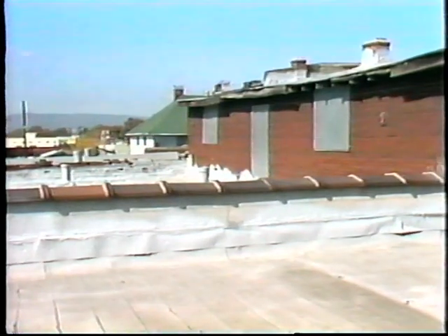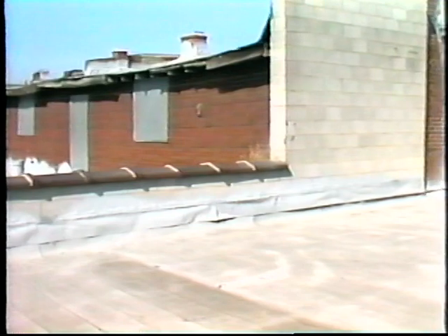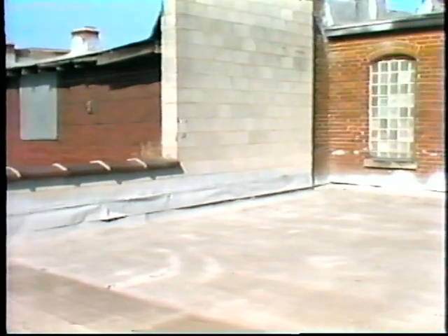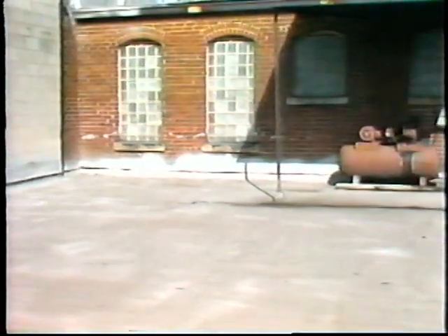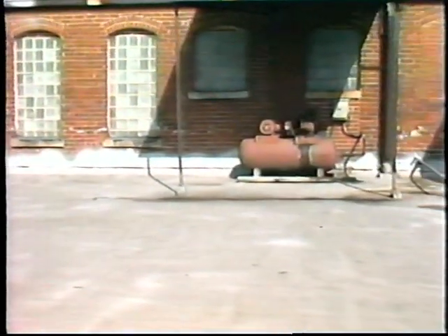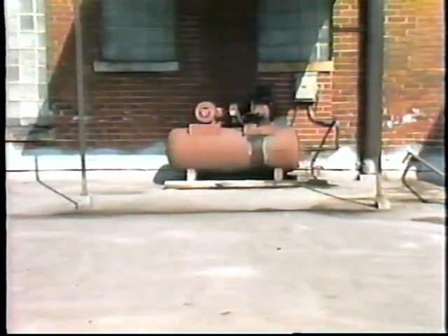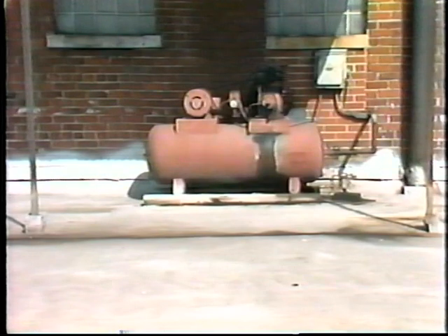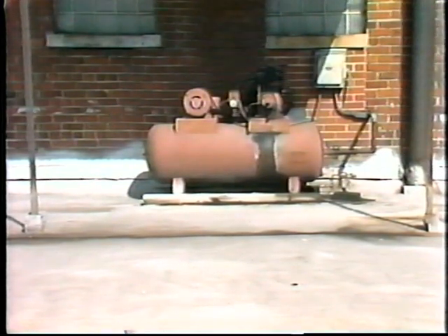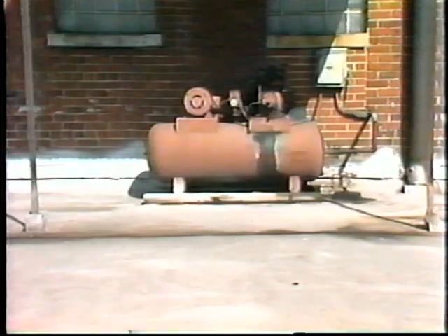Have you ever been up on the plant roof on a summer day? If you have, you know how hot it can be, particularly if the roof is black. This is not the place to locate an air intake. As air temperature increases, its volume increases, and the compressor has to work a good deal longer to deliver the same capacity. So locate intakes where the air will remain as cool as possible.